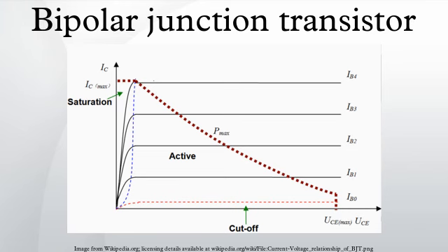For common emitter mode, the various symbols take on specific values: x equals e, because it is a common emitter topology; terminal 1 equals base, terminal 2 equals collector, terminal 3 equals emitter; Ii equals base current, Io equals collector current, Vi equals base-to-emitter voltage, Vo equals collector-to-emitter voltage; and the h parameters are given by hix equals hie, the input impedance of the transistor.